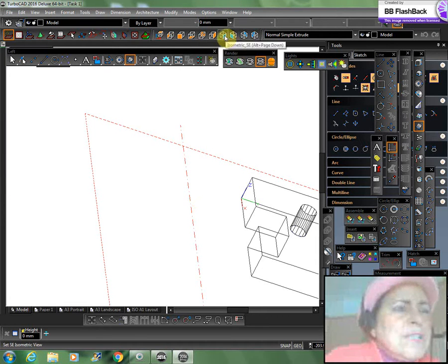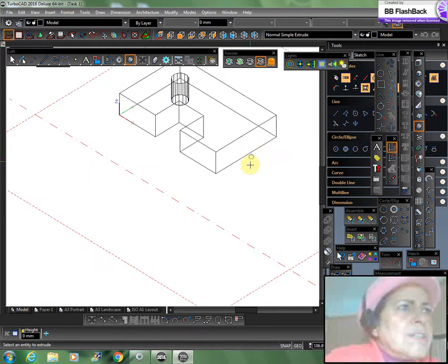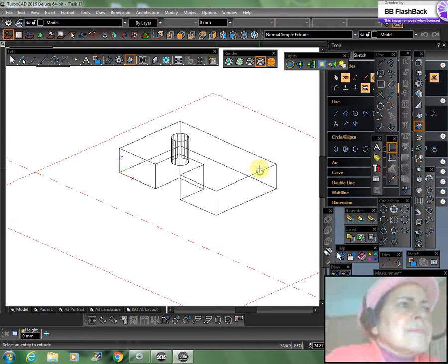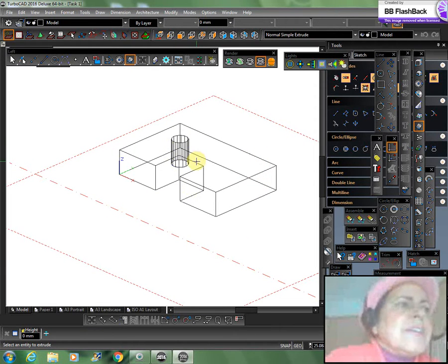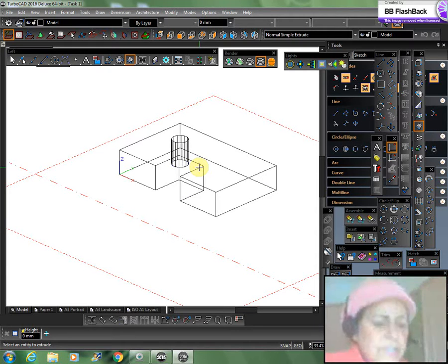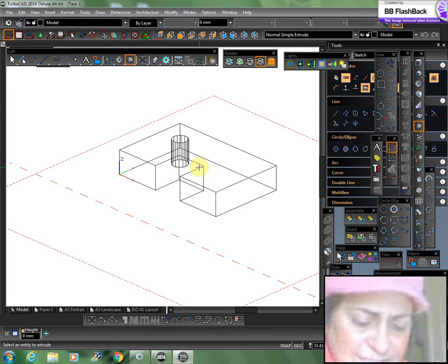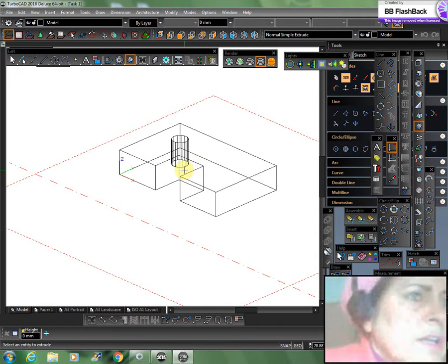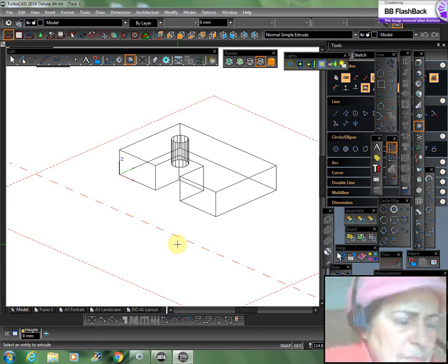I press southeast, so it sits on its plane like this. This hole is created, and that is called extruding downwards. There are other ways of creating a hole, by Boolean facet tools and 3D Subtract, but that is not the subject of this lesson.